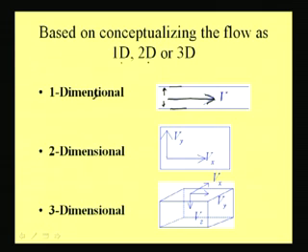Now, in some cases, suppose a flow is occurring in a wide valley, there may be a significant component of velocity in both directions. Let me give you one example. Suppose this is one river and there is another sub channel which is also wide, or suppose there is an embankment and it has failed somehow and the water from this side has flown into that side. This we can also consider as open channel as it is flowing over the surface, and it will be moving like this, and in that case the velocity in this direction Vx and the other direction Vy are also significant. So, we cannot neglect the flow in the lateral direction. That we call a two dimensional flow.